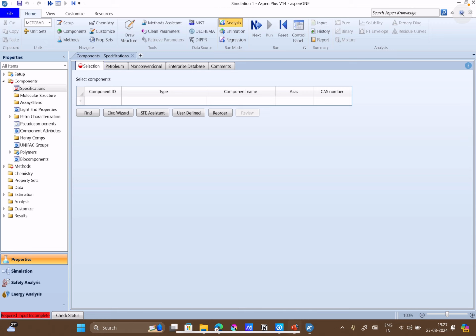Okay. Now can you shift this to mass percent, or should we be able to see it in mole fraction? No, generally it's with mole fraction, so that's why it doesn't allow you to change. And mass fraction again, I don't think so. The mole fraction is the correct approach here. Can you go to the ternary diagram? Industry wants it in weight percentage. Okay. I'm not sure whether ternary diagrams are used with weight fraction, but probably. Can you go to the ternary diagram plot? Or should we change this mole fraction to mass fraction? Yeah. If you have enough data, you can change it. Right now we haven't specified anything, right? We don't have any flow rate or anything.